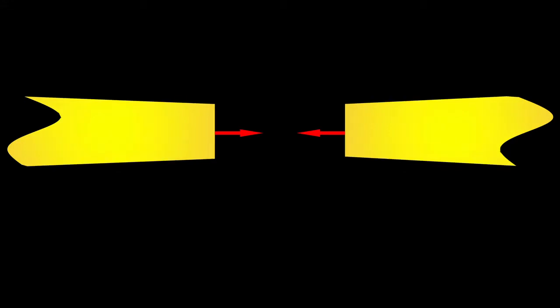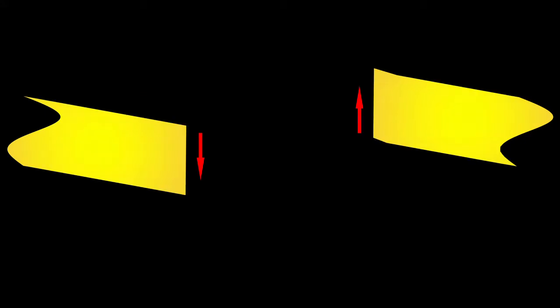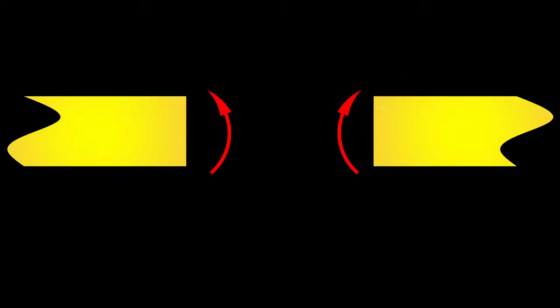To inspect the internal forces, we will cut an imaginary section through the member. By doing so, we expose three forces acting on the face of the section, which are axial, shear, and moment. We consider tension to be positive axial force, just like what we do for truss members. Shear force is positive if it tends to rotate the structure in clockwise direction. For bending moment, we regard sagging moment as positive and hogging as negative.